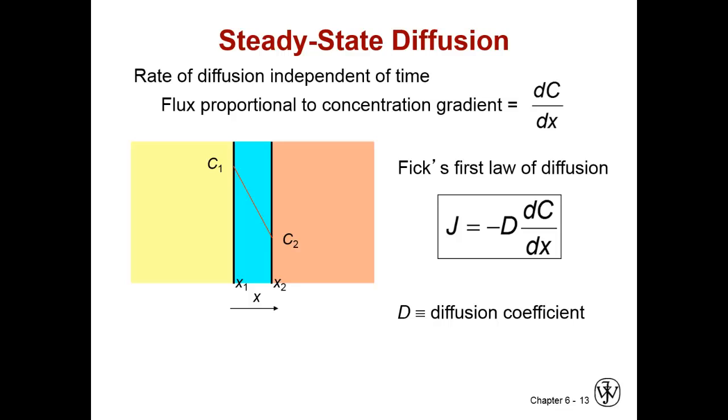We also covered flux, and that's what this J here stands for: the flux is proportional to the concentration gradient. So if there's more on one side, less on another, you'll have a higher gradient, which will give you a greater difference here and lead to a higher flux, J. Now what's very important in this equation is this right here, the diffusion coefficient. The diffusion coefficient has its own equation associated with it, so we're going to dive into that next.